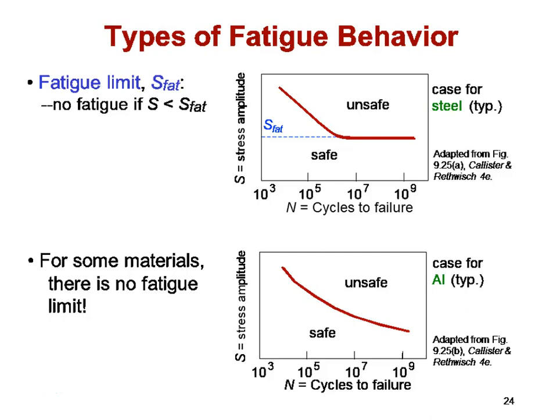And as luck would have it, the materials that tend to have fatigue limits, that have that stress below which you can cycle it forever without having a fatigue crack propagate, are body-centered cubic materials. So, of course, these are the ones that don't do quite so well in ductile to brittle transition, so there's no free lunch there. But if you don't have to worry about drastic temperature reductions in service, and you have cyclic loading, or a particularly severe case of cyclic loading, you might, for instance, want to pick a steel over an aluminum, just as one case in point.